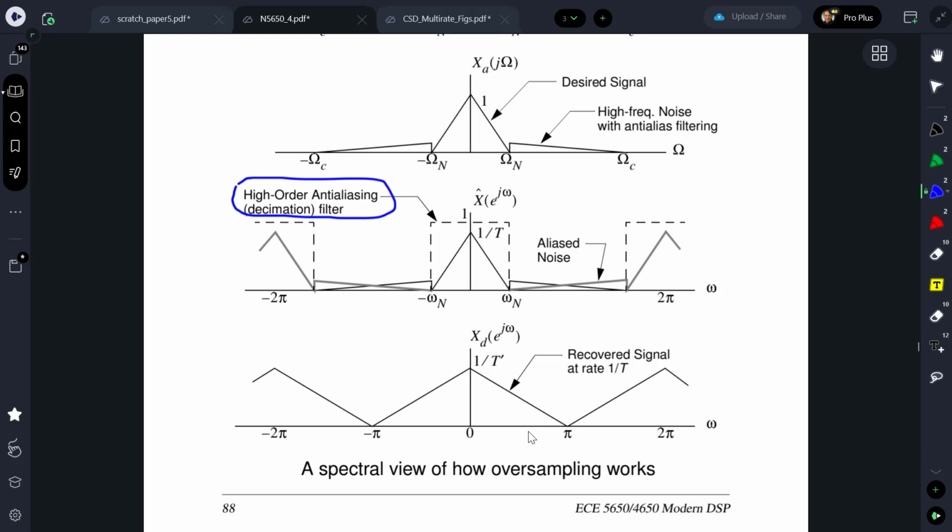It will sample at maybe 64 times in an analog, or an audio application chip. And then not only that, it doesn't have to require, say, a full 16-bit conversion. It can do it with 1 bit. And that's the amazing part about the sigma delta. It can be a 1-bit converter, oversamples at a high rate, and you end up with a very nice output at that point.